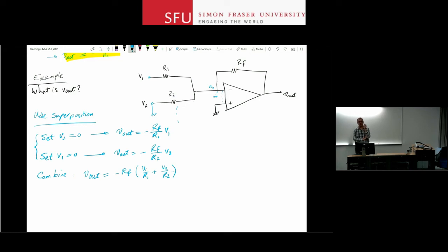It could be 1K, and those guys could be 5 kilo ohms. So what happens is that the output of this circuit, you will have 1/5 of V1 plus 1/5 of V2 plus 1/5 of V3, and so on and so forth. And therefore you get your average right away without doing any calculation, in almost real time, right?